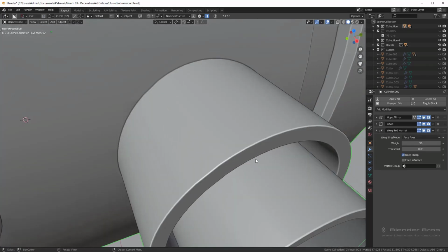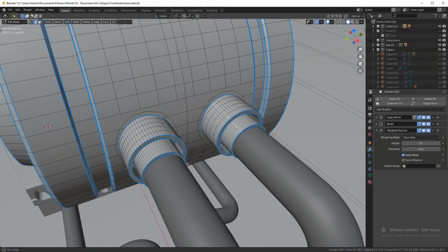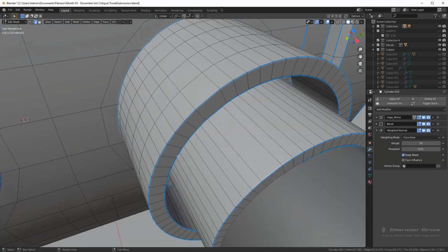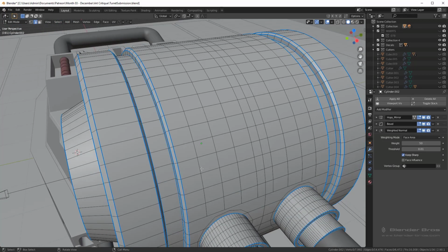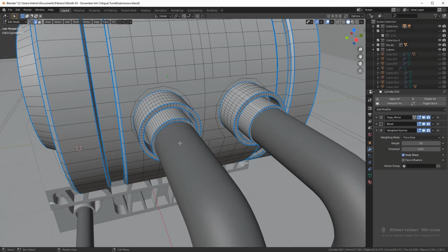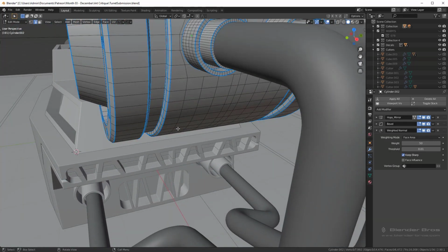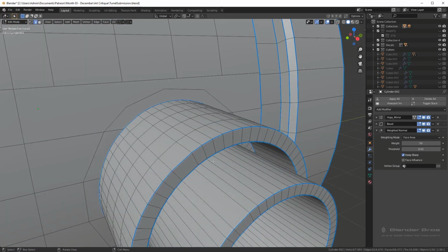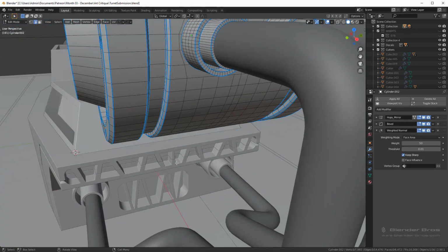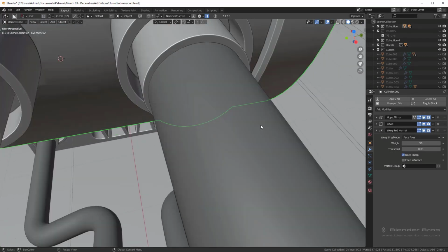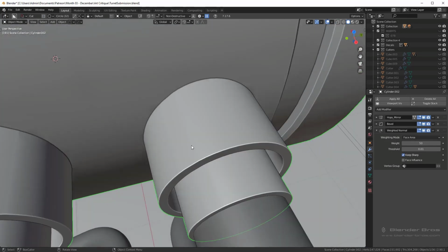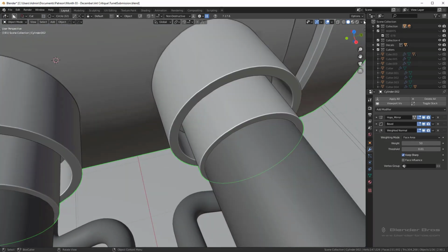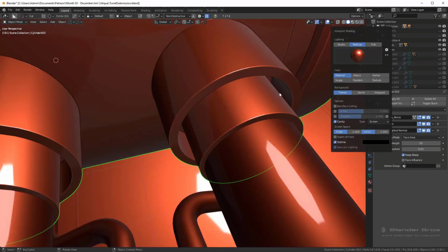Now right here, I think it was just, okay. One thing I did notice was this. This is problematic. So I can tell you were trying to kind of cheat the system here to fix up the shading, and you got kind of close to a good result, but not quite what I would have gone for. So first of all, this right here is killing the curvature, and you can see that visually. I'm not sure if you can see it in YouTube's compression, but see that very visible line? This is obvious. If we go into matcap, you might see it better.